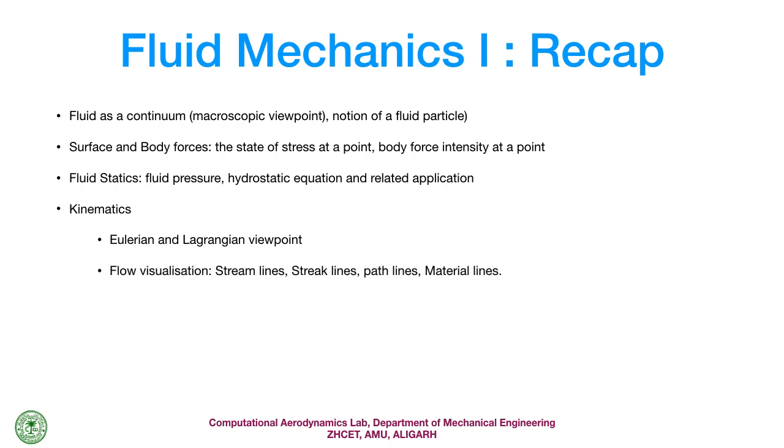Now, you might have also studied flow visualization, that is streamlines, streak lines, path lines, and material lines. These are the tools of how we can visualize the flow. Streamlines are imaginary lines such that the tangent to that line gives you the velocity vector.